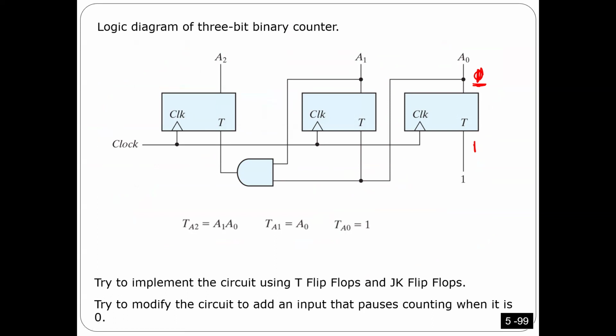That doesn't mean for everything I should have an observation like this one, and I don't need a state diagram all the time. No, it's only here. So if I add 1 more here, that means I'm going to need AND, without even making a state diagram or whatever, because I have a certain observation here. Then here I will connect A node, I will connect A1, A2, so that this one is going to toggle when all of them are ones. When at least one of them is 0, there should be 0 and no change. Anyway, same thing, you can extend it more if you want.